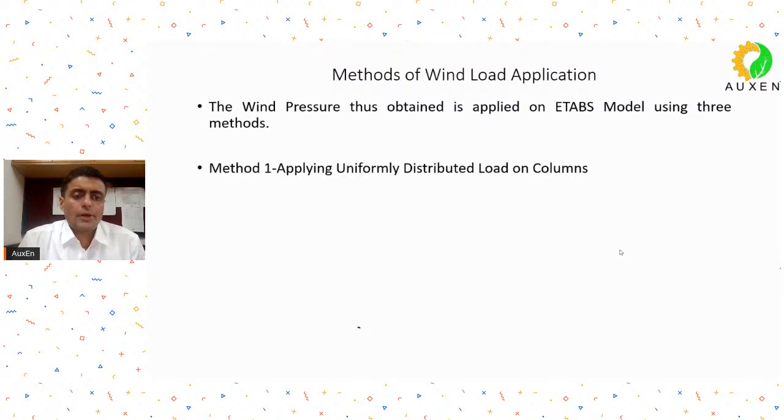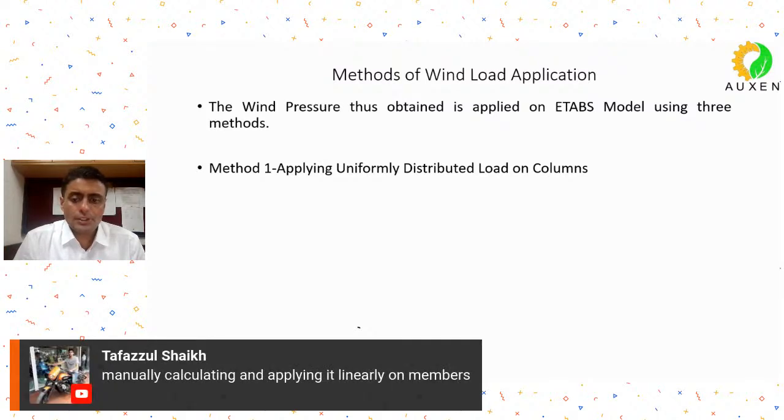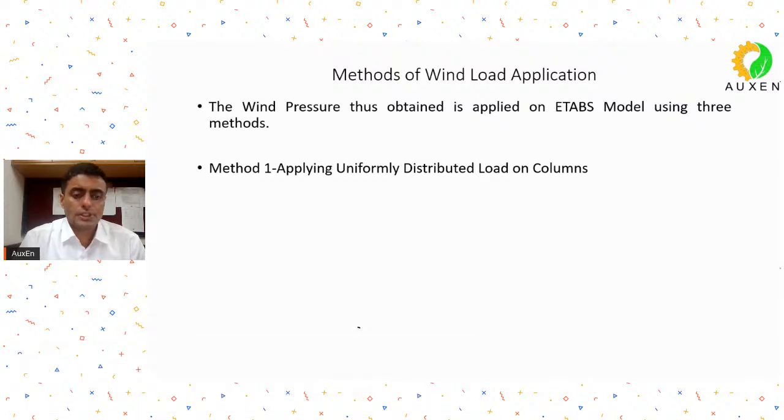So method 1, we will apply the wind loads as uniformly distributed loads, and we will apply them on columns. What Mr. Tafazzul is saying, manually calculating and applying it linearly on the members. So this will be our first method through which we will be applying wind loads. Remember what we are doing in this discussion, we are going to apply wind loads using different methods, and then we will compare the outputs,